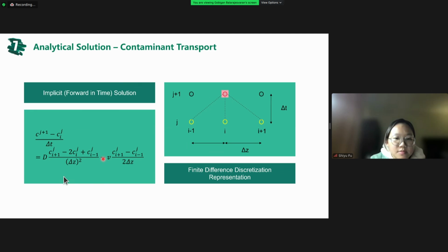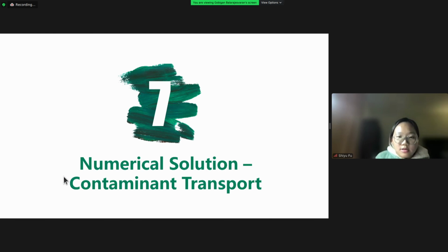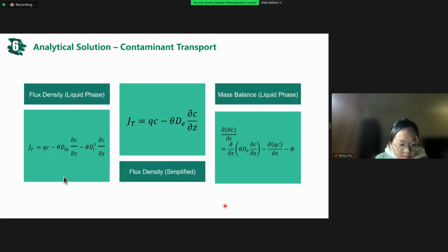Because the theta changes, and we know that for Darcy's law, K is constant, but this time when the theta changes, the hydraulic conductivity will be changed with the material. When the theta changes, the hydraulic conductivity has changed and will influence it.